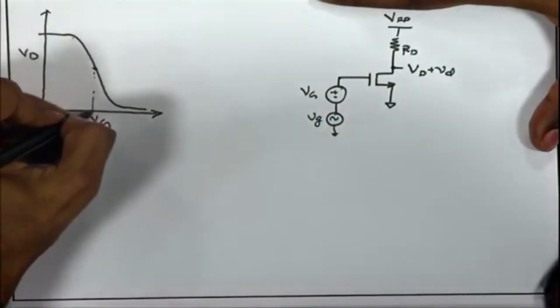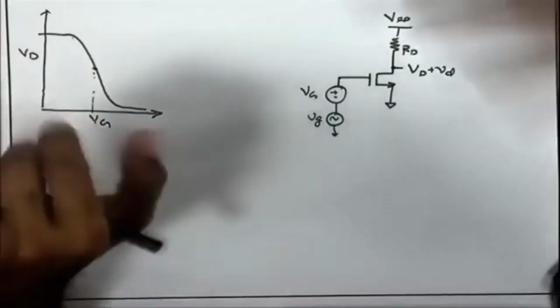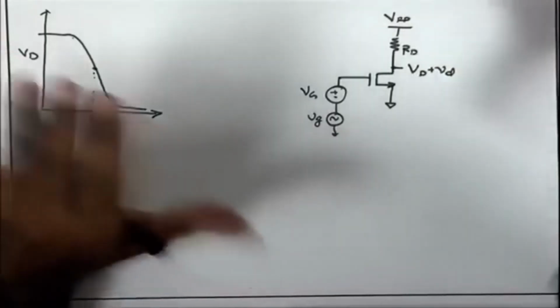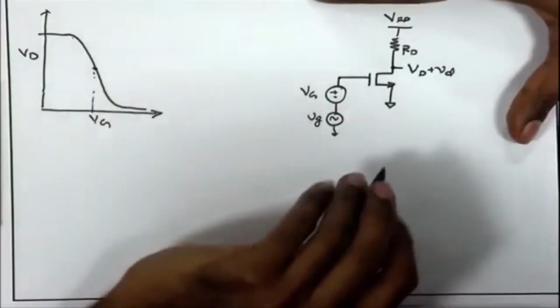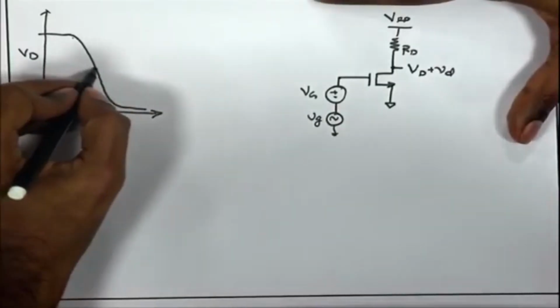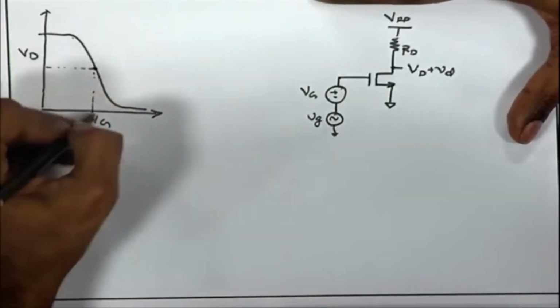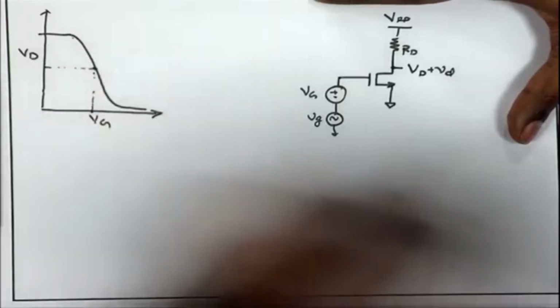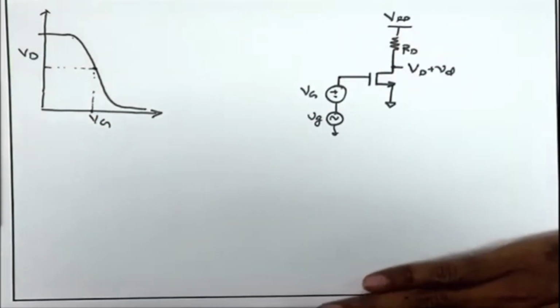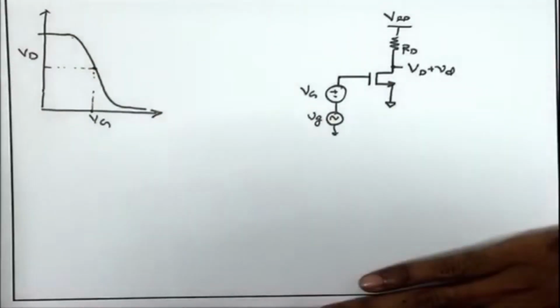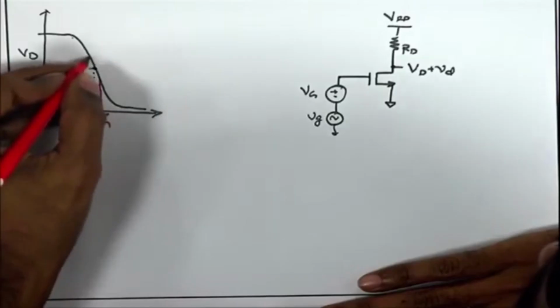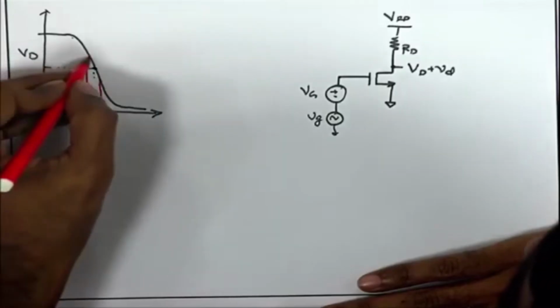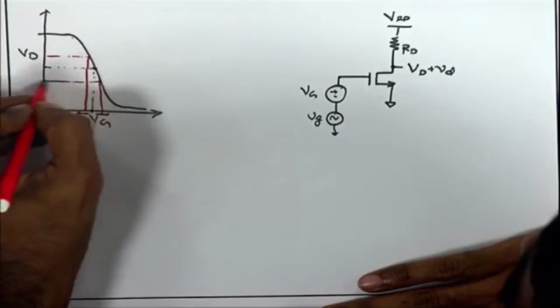we are fixing the DC bias point. In order to operate this circuit as an amplifier, the first thing once again is to fix the DC operating point or the DC bias. So, we fix the Vg, and corresponding to that I also have the Vd fixed. The DC voltage at the gate and DC voltage at the drain are getting fixed, and on top of that I am going to apply a small delta Vg plus minus,